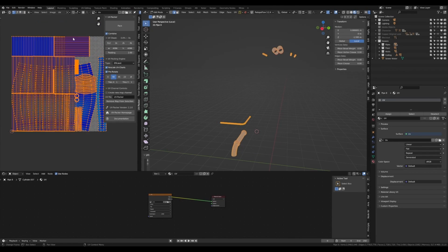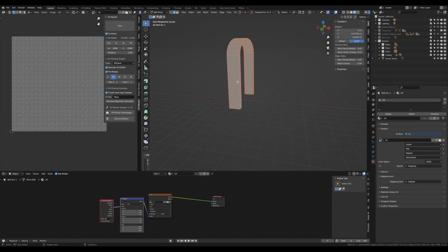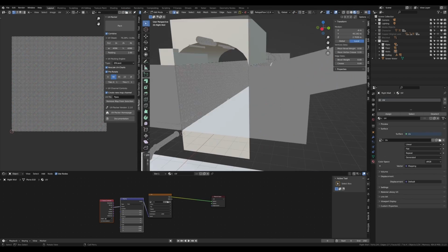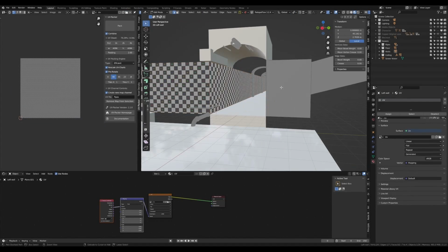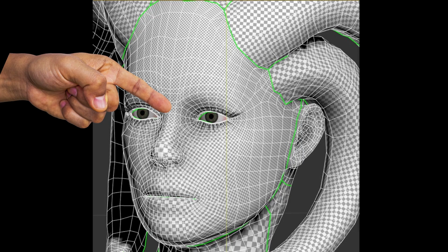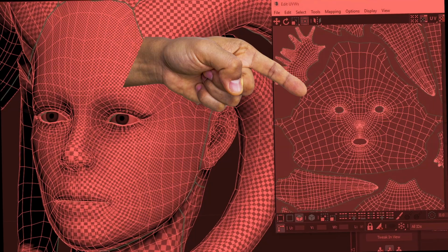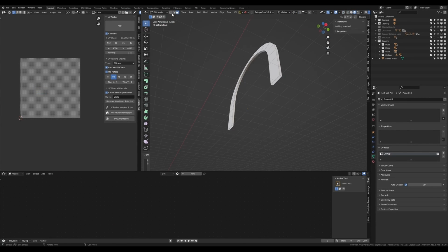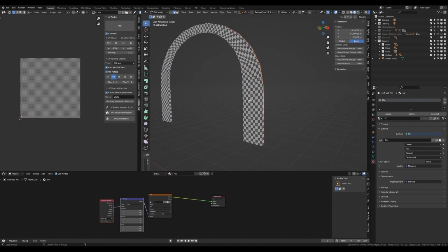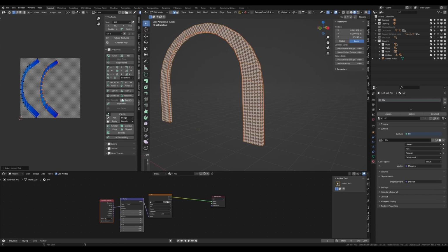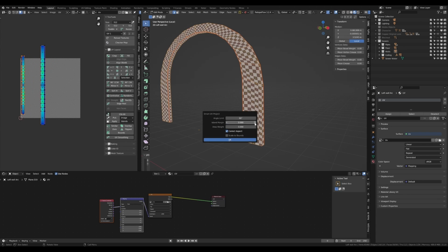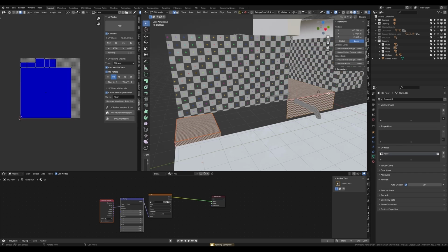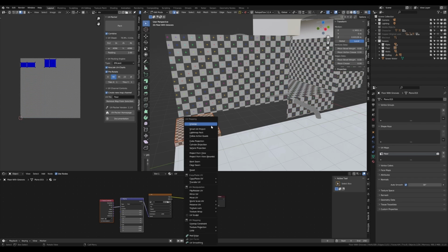And if you don't know what this is, it's basically flattening out our 3D models into a 2D shape so that we're able to wrap a texture around the model properly. Yeah, this process can get real freaky when you go from seeing your model like this to it looking like this. For this, I'll create a 4K UV grid texture which I will apply to all my objects as I unwrap them, and this will let me see if I'm doing a good job or a bad job.